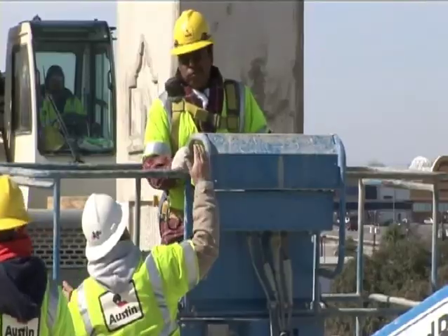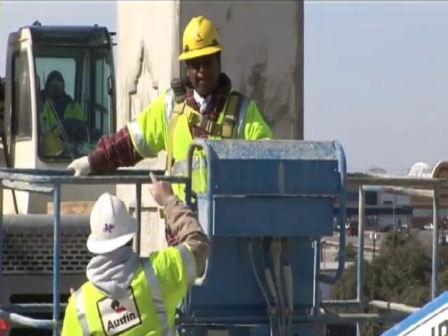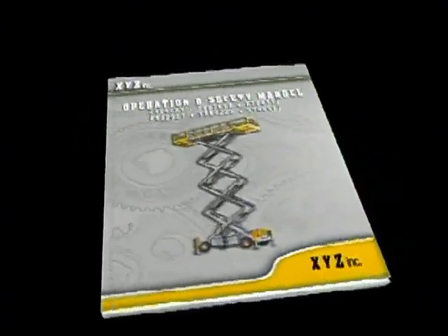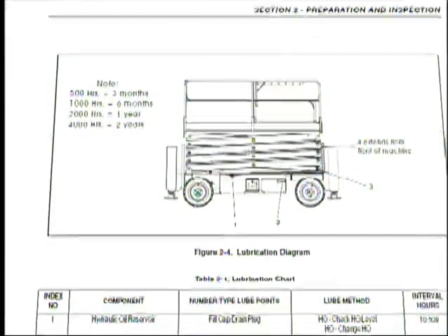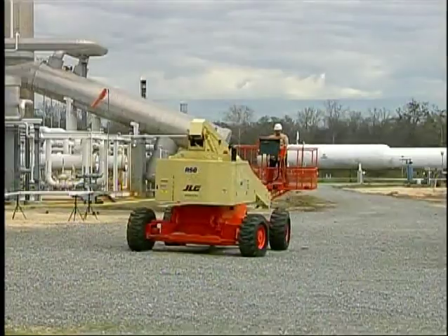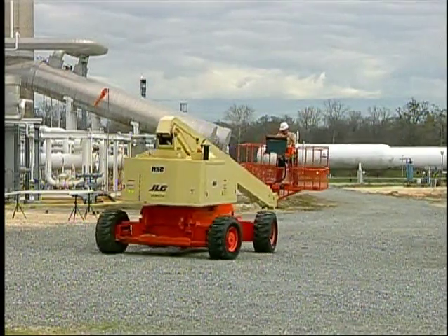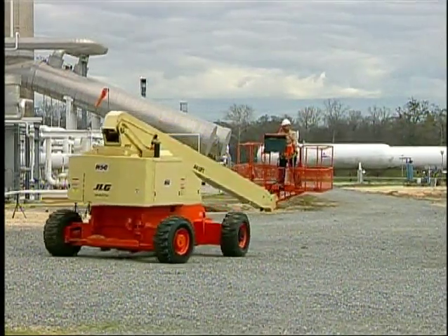The employer is required to document the training and give the training on a periodic basis. Employers must ensure that employees are familiar with the lift they are asked to use. Employees must be provided with an operator's manual and a maintenance manual for the lift being used. Employees should become familiar with the manual before operating the lift. All employees who operate lifts must demonstrate that they understand how to use the lift. Any employee who does not understand the lift or the skill or understanding needed for safe operation must be retrained.